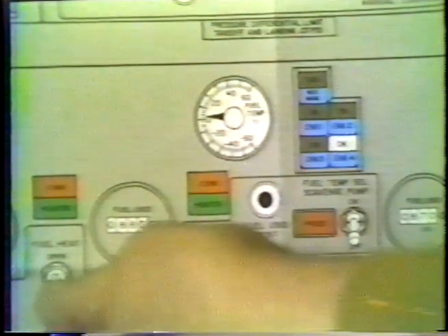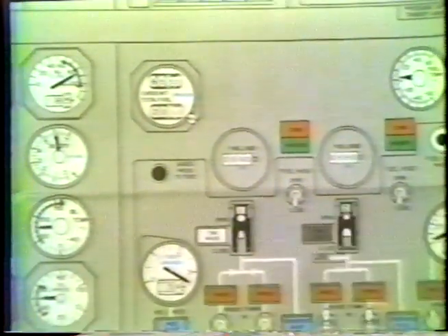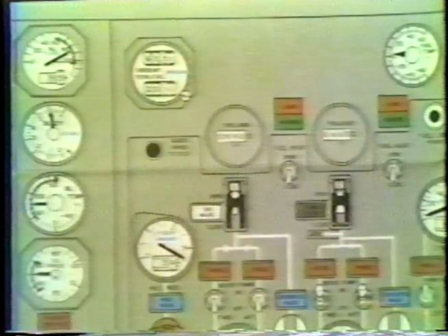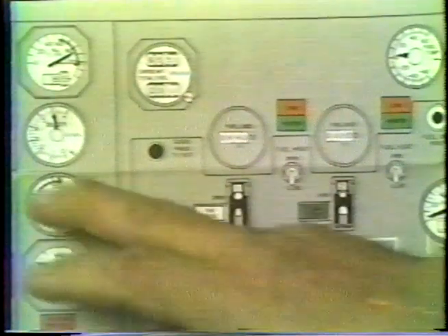One of the solutions, if the fuel valve is stuck in the open position or does not properly close, is quickly move the fuel heat switch to open and then back to close again. You might try this several times. And of course, if it does not bring this fuel temperature back down into the green band, the engine should be considered for shutdown.